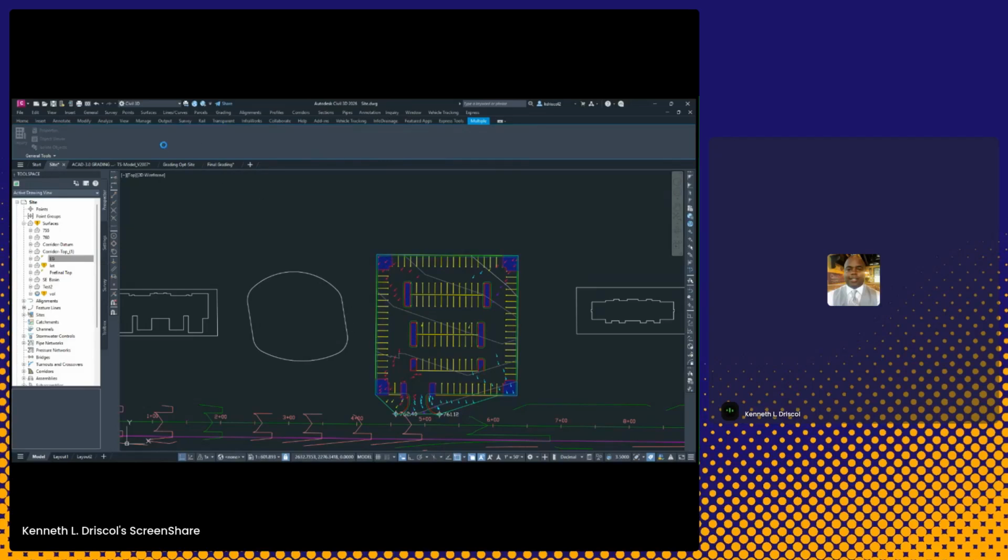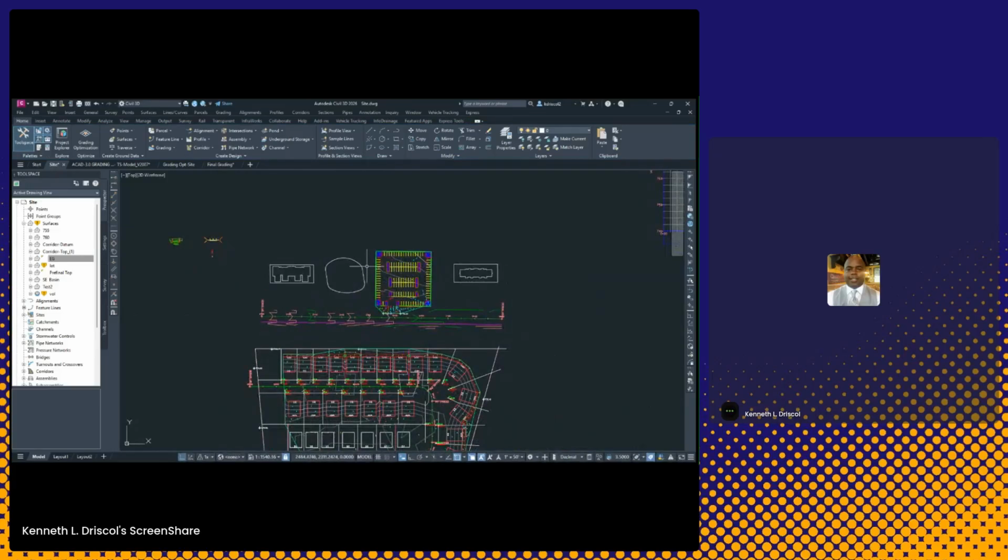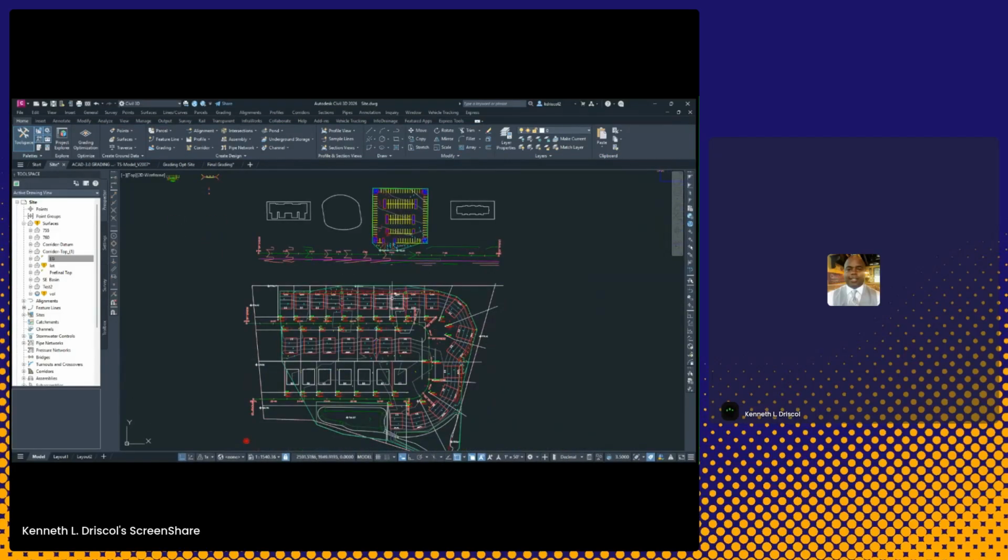And I'm doing things pretty quick. Okay, so now we have this in terms of we got our curb and gutter in our parking lot. So we just add this, create a surface from it. Pretty straightforward. Now, doing all these things, I would have put a pond here, a building pad right here. This, again, takes probably this whole site a week.